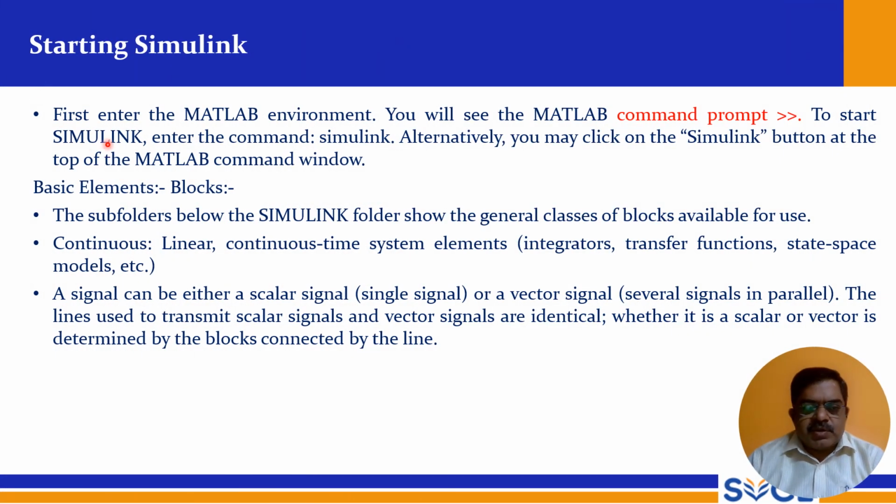So starting Simulink, first enter the MATLAB environment. You will see the MATLAB command prompt. So this is the double arrow. To start Simulink, enter the command Simulink. Alternatively, you may click on the Simulink button at the top of the MATLAB command window. So basic elements, blocks: the subfolders below the Simulink folder show the general classes of blocks available to use. So continuous: linear, continuous time system elements, integrators, transfer functions, state space models, etc.